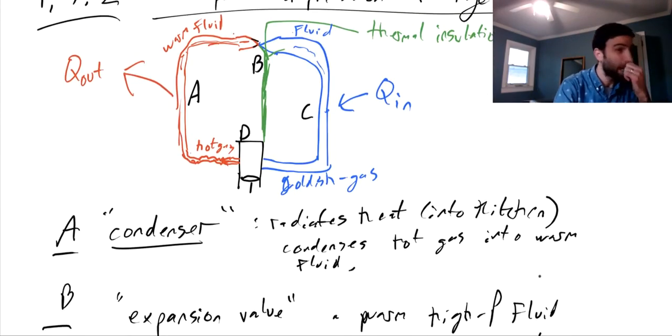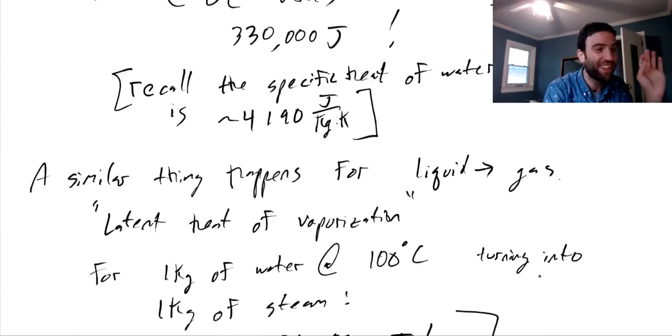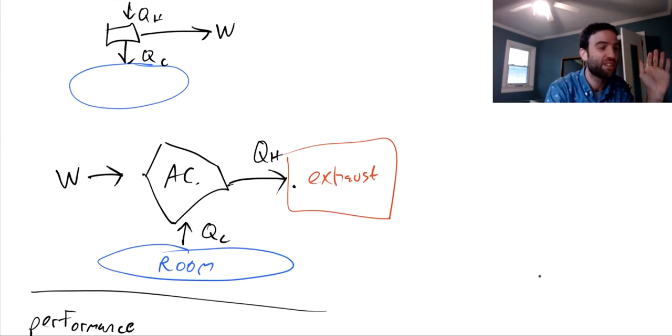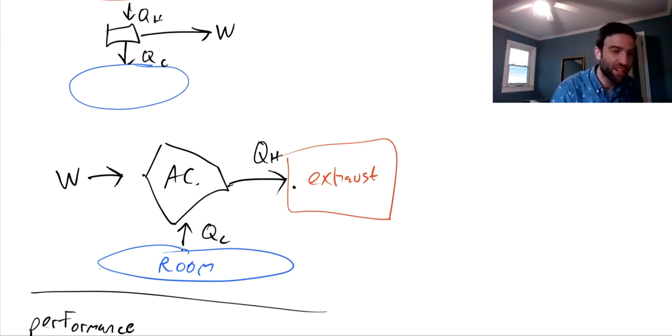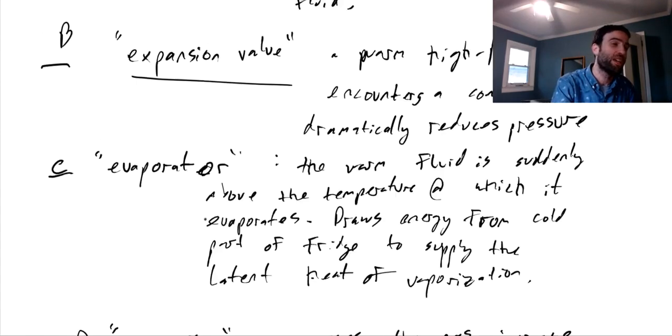And again, let's think about this in the context of these idealized schematic diagrams we put in the first place, where we said any refrigerator, any heat pump, is basically something where you feed in work, and then as you feed in work, it takes heat from somewhere that's already cold and dumps it out into somewhere that's already warm. And that's what we're doing in this cycle.